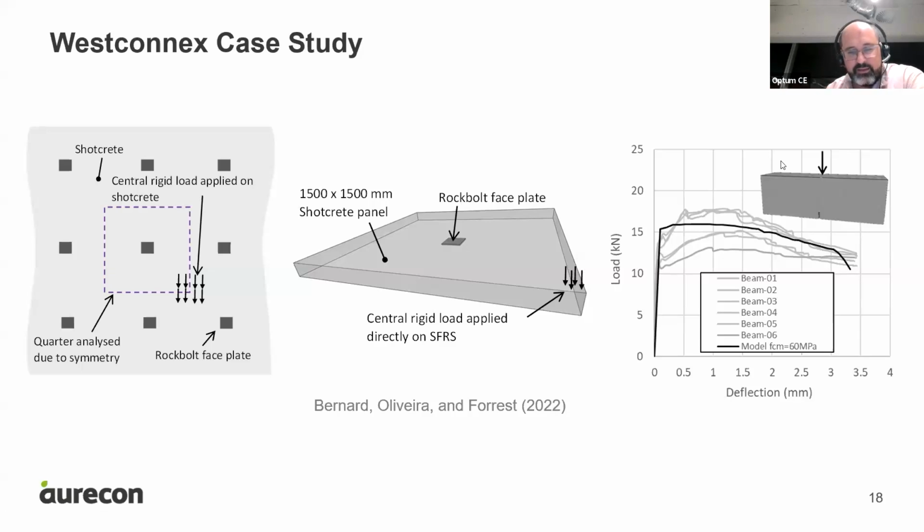When we're developing the mix, there are tests that are done in terms of the mix. It's not just simple compression. We do a lot more than that. We do obviously our compressive strength testing. We do indirect or the Brazilian testing to get indirect tensile strength.